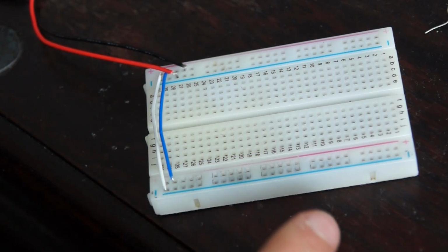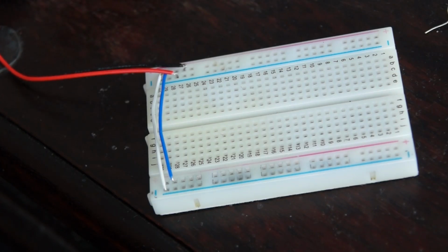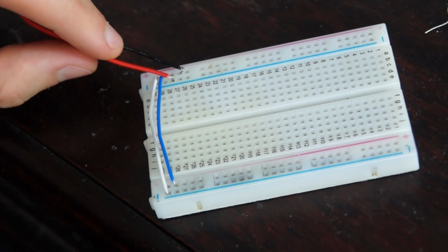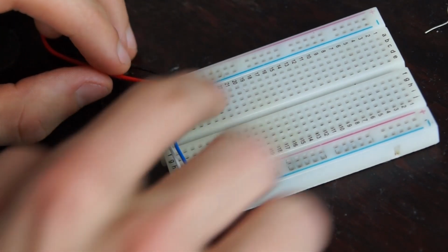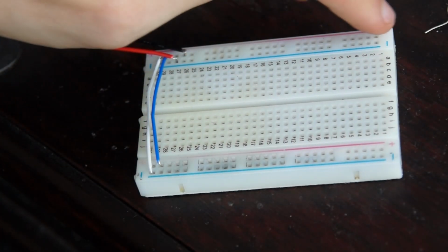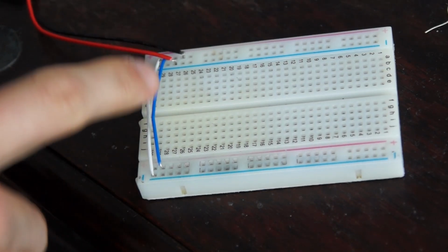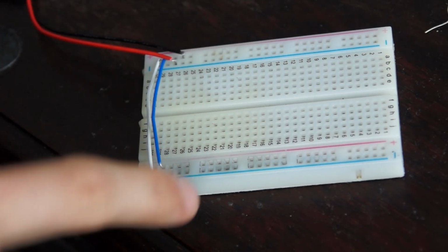So we've got our breadboard here, and I'm going to do something that might look a little bit weird. I put my positive end in the negative rail because I'm just used to the negative being ground, and the positive will be minus 9 volt now because we're working with a PNP. So we need a negative voltage to supply our circuit. I also connected these rails with these ones on the bottom here.